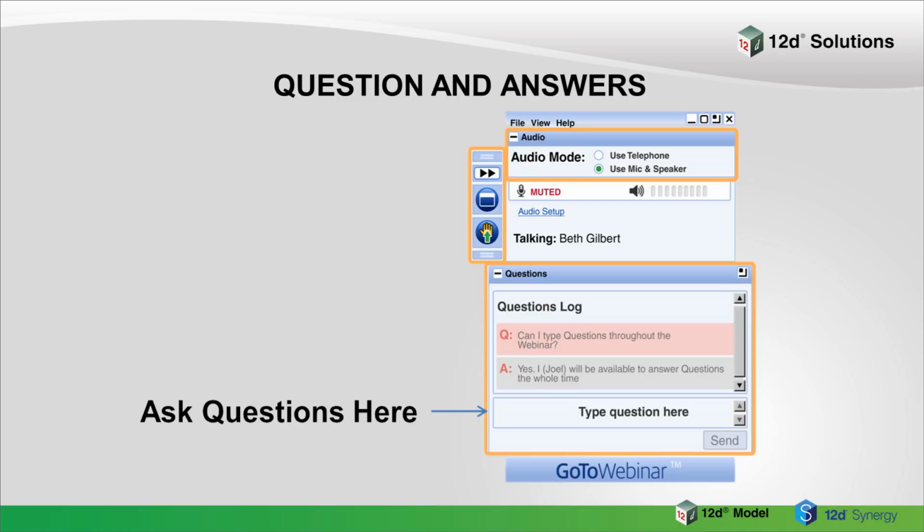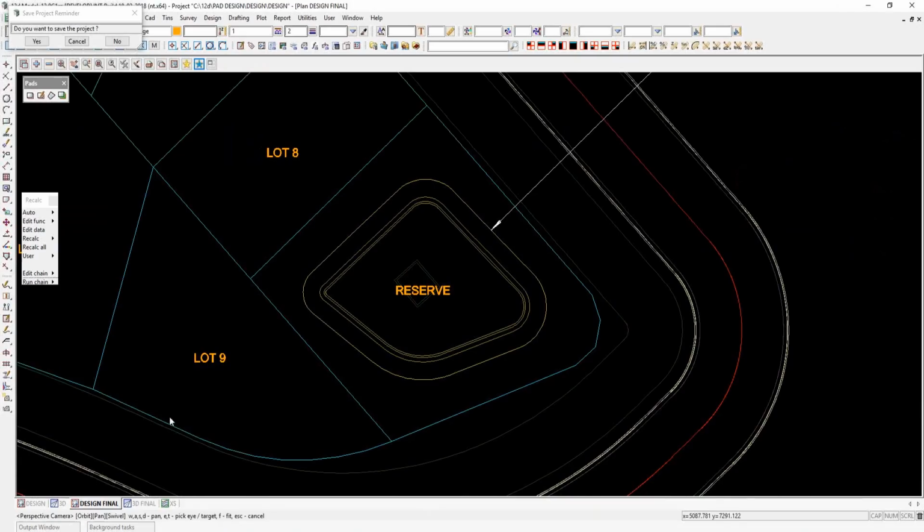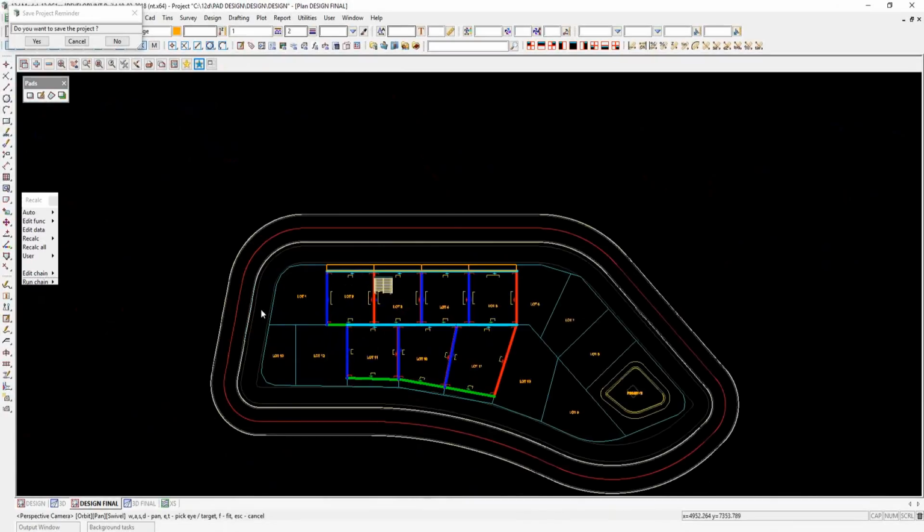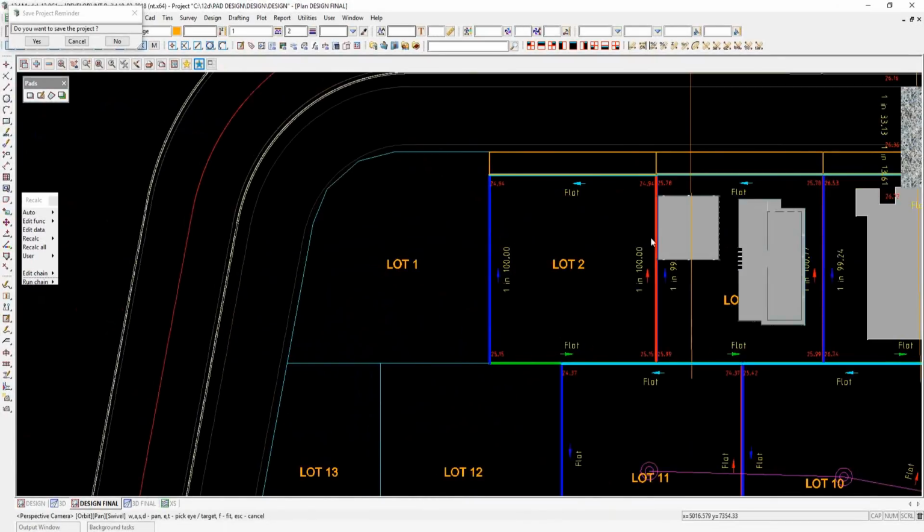Ben has asked, what would be the process for creating a building pad with 2 levels, so a step in the pad? Yeah, as I just mentioned, I must have preempted you, Ben. You just have to create the 2 pads similar to what I've done here with these walls. So you'd end up having a pad here, and there may be another pad inside like that, and then you just triangulate, and it depends on whether you want to divide it all up into little tiny areas, but at the moment you wouldn't be able to have a hole in there.